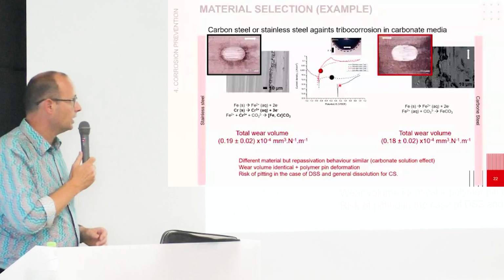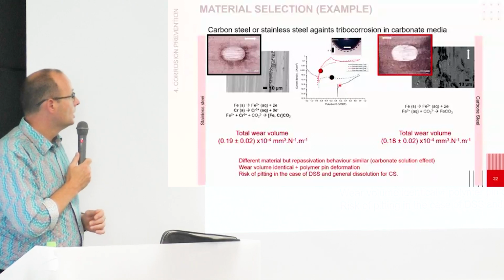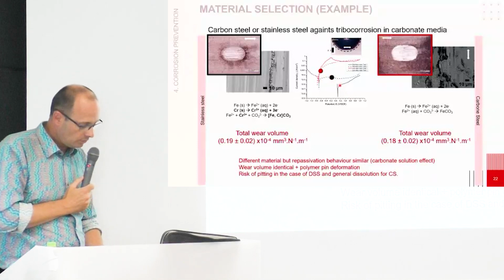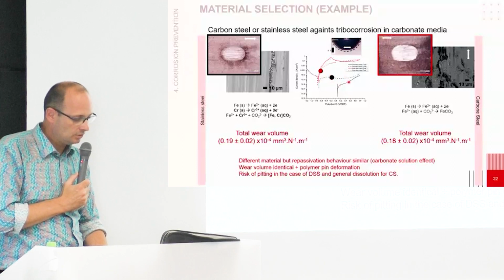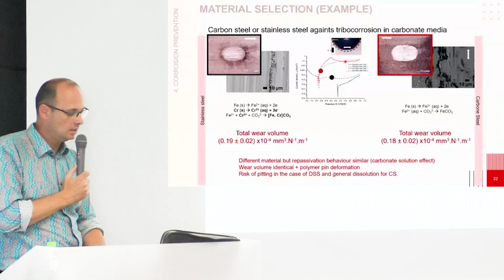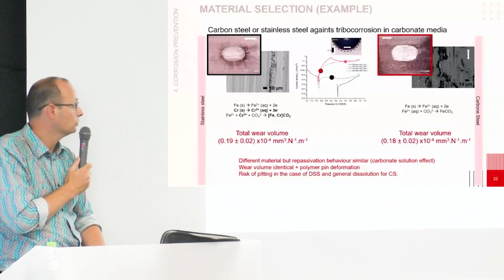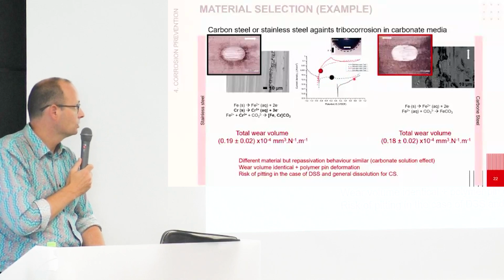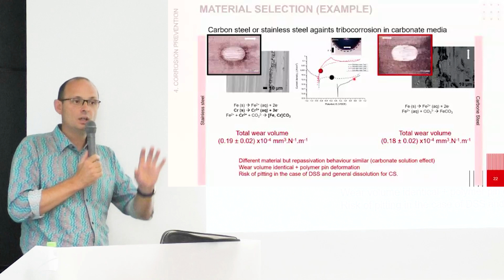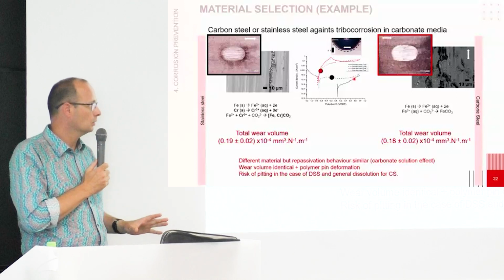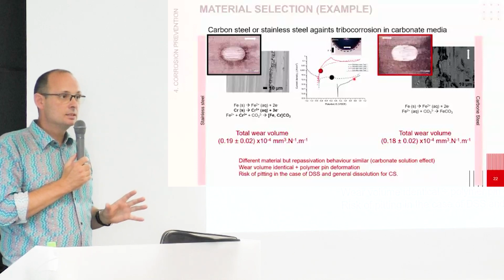In black, this is the stainless steel. If you look at the curve, and we will look only at this part, for example, you can see here I have a lot of current flowing from the electrode, here less. So that means that in this environment, in static condition without mechanical load, stainless steel is better.